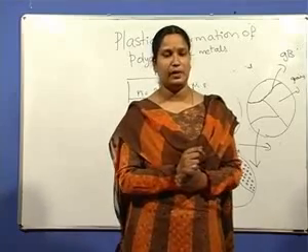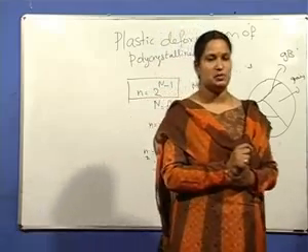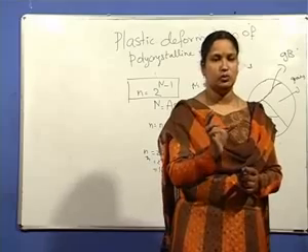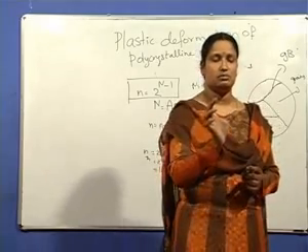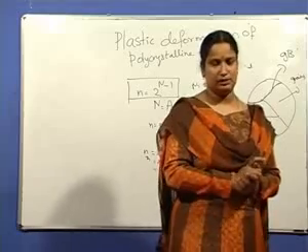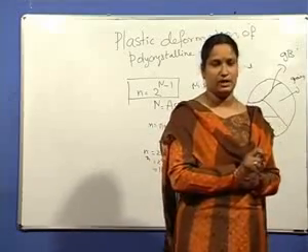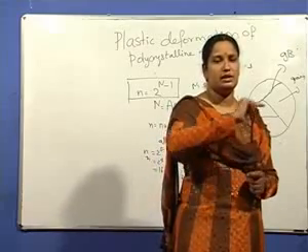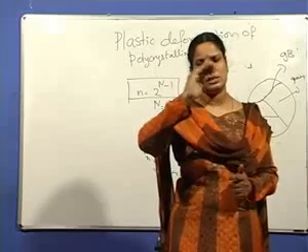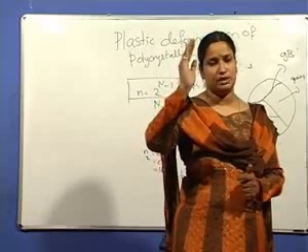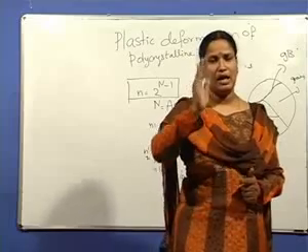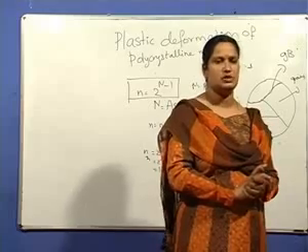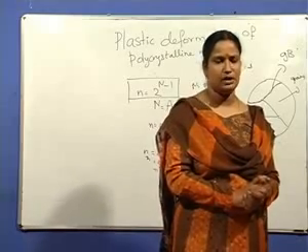Stress is calculated by load divided by the cross-sectional area of the specimen, and strain is the change in length, that is the extension divided by the original length. So the stress versus strain graph has been discussed. You have seen that the curve increases to some point, that is strain hardening that takes place in the material, and then it drops down. That is the normal curve, the general curve that is observed for most of the materials.